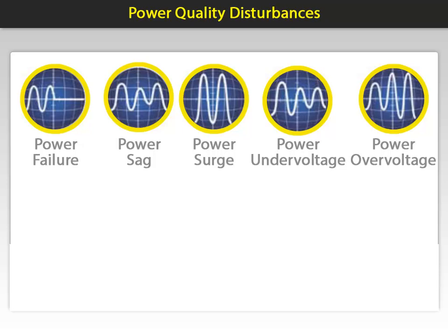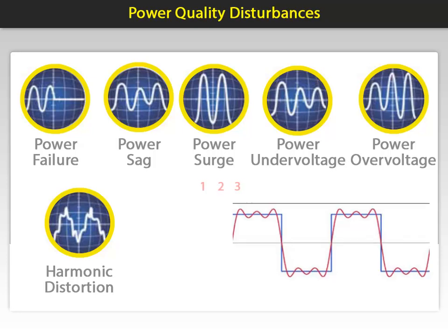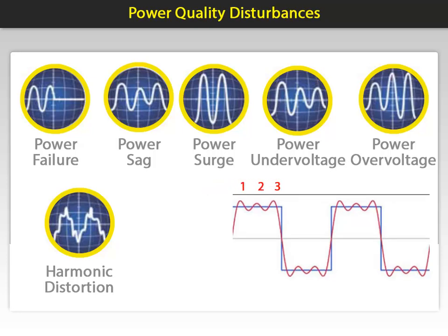Harmonic distortion is the presence of unwanted frequency components in a power system. These unwanted components are integer multiples of the fundamental frequency, usually 50 or 60 Hz, and can significantly impact the performance and reliability of the power system. These multiples of the fundamental are displayed in the waveform. For example, this image shows a multiple of third harmonics. To better understand and provide data to help eliminate this, a calculation is available to ascertain the total harmonic distortion, or THD.